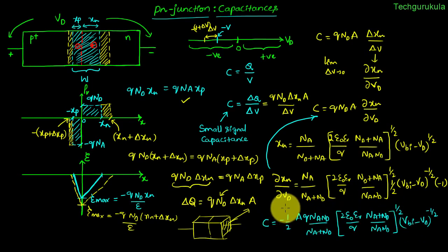But it is surprising to see that we get a minus sign. But in fact, the capacitance definition is the amount of change of charge stored per the change of voltage applied. We're talking about just the quantities. So we really don't care about the minus sign. So we should be taking a magnitude here.